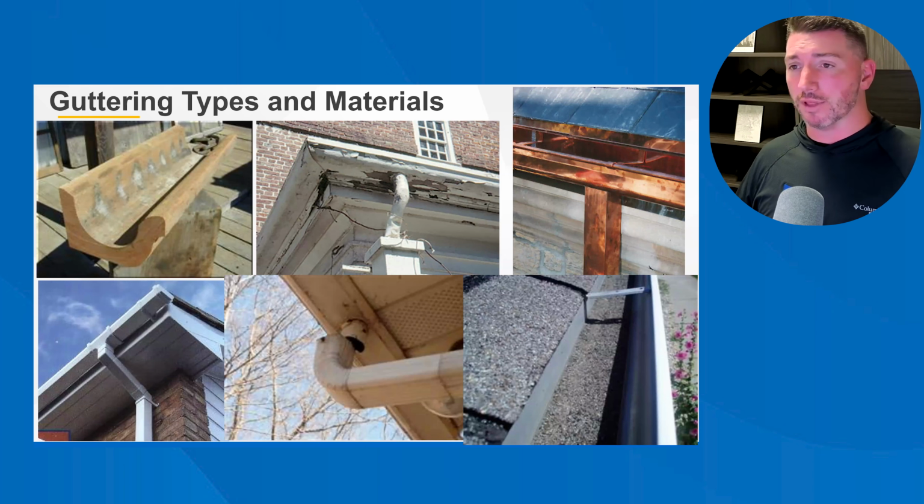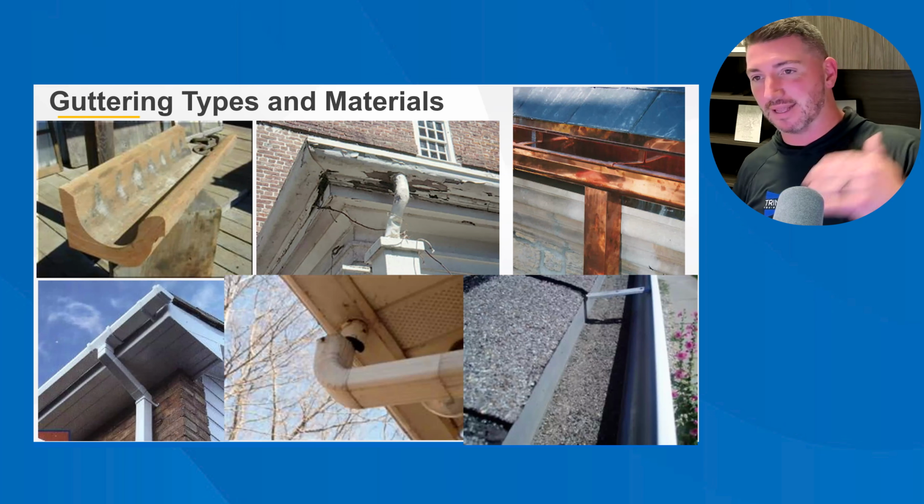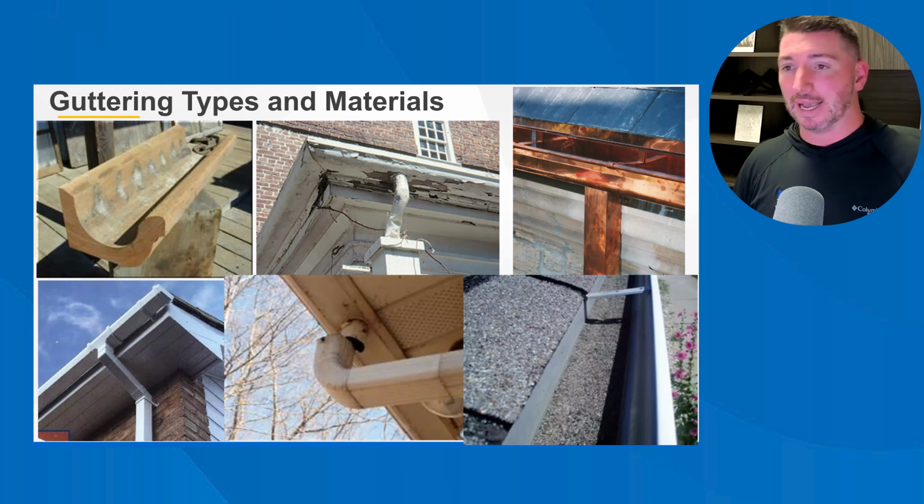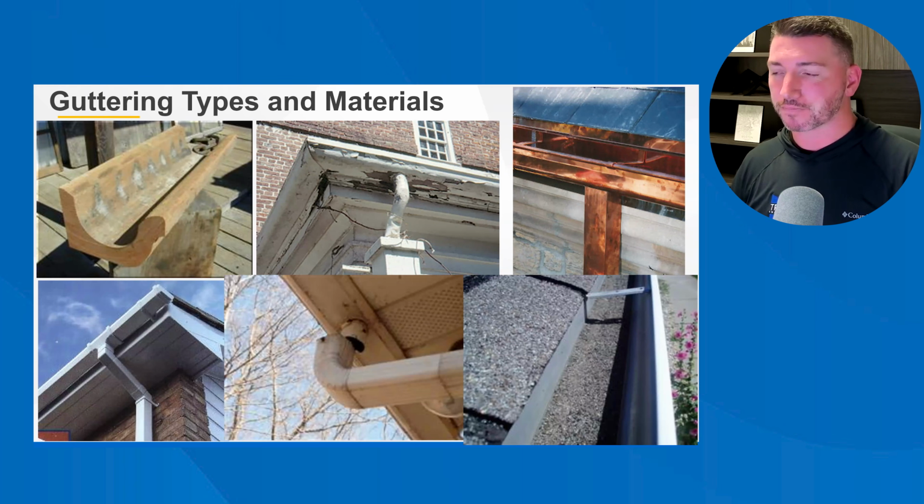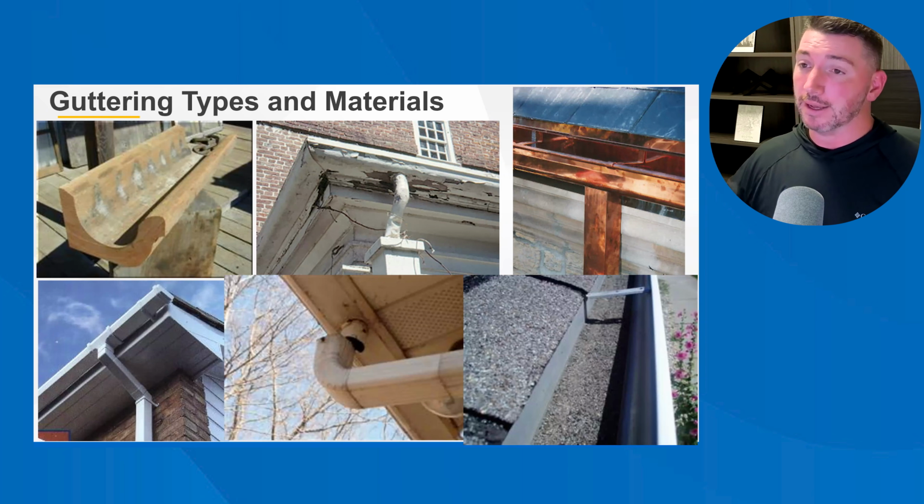And then if you don't already know this, roofs tend to break down and the breakdown accelerates as the roof gets older. And I don't just mean that there's more breakdown when something's older. Of course, that makes sense because if it breaks down every 5 years, every 10 years, by the time it's 20 years old, it's obviously more broken down than it was when it was 5 years old. But specifically, what I'm referring to is that the amount of breakdown of a roofing material from 0 to 5 years is much, much less than the 20 to 25 year mark. So it's like a reverse snowball effect, if you will. As the roof gets older, it degrades faster. So you'll see a lot of surface aggregate in an older roof.